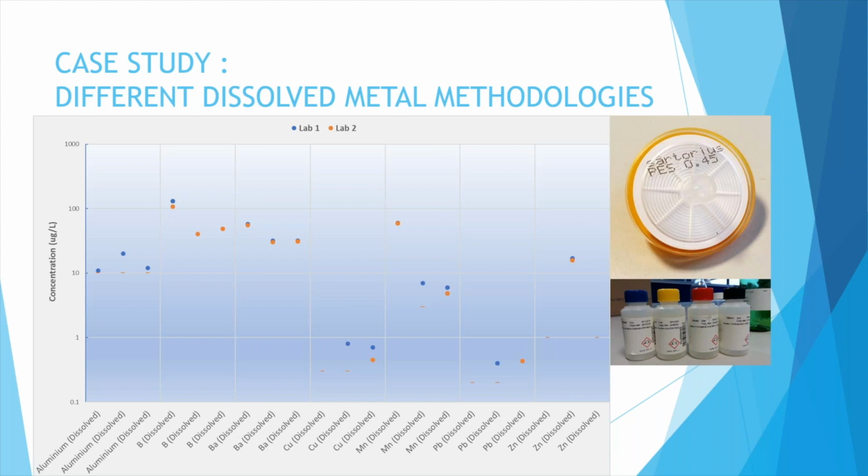Now, the concentrations of the results are shown in this plot for a number of different heavy metals. This is just a subset of the samples that I've provided for this slide. The concentrations are shown in micrograms per litre on a logarithmic scale on the left-hand side. The symbols that are a bar, like the orange bar you see there, show the level of detection. This is the minimum level that the laboratory can report. And the large dots are detections that were made with the laboratory analysis.